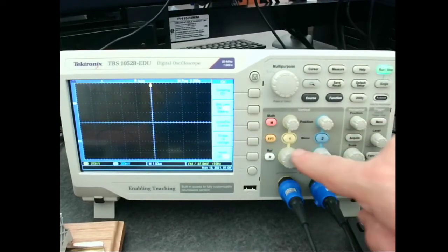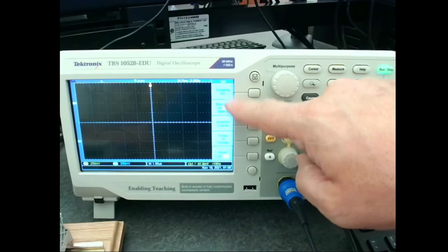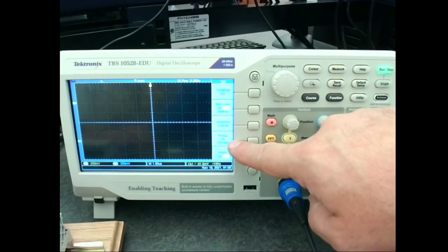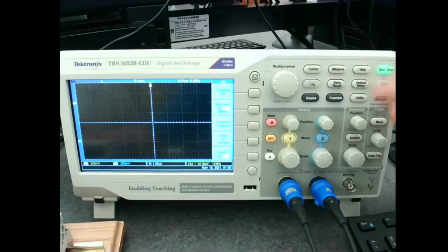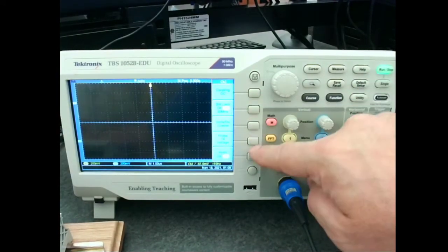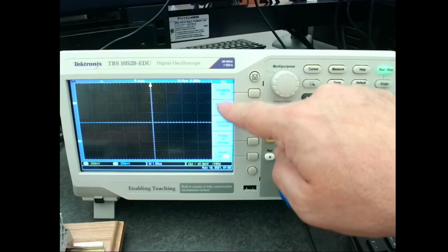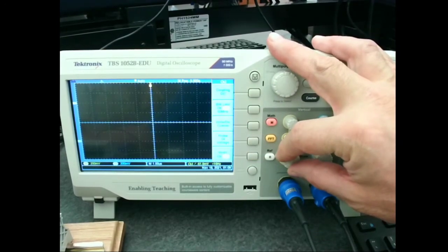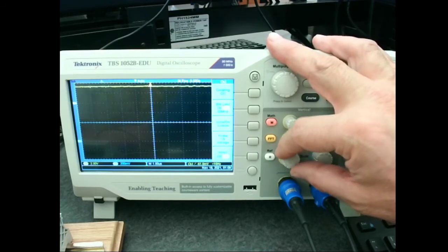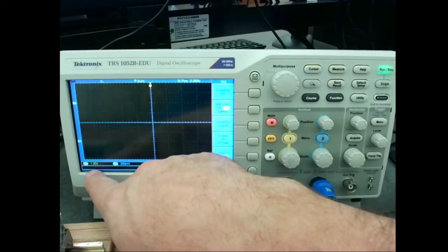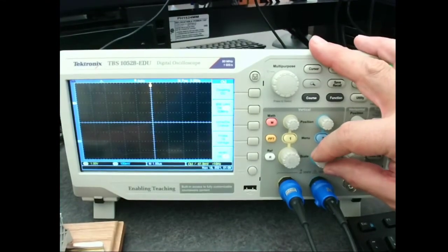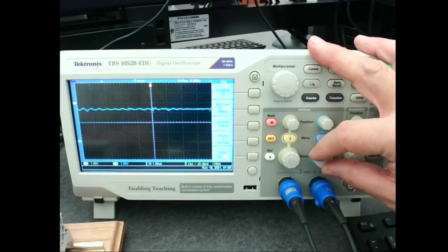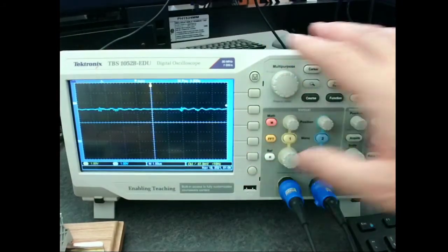All right. So again, let me walk through setting this up. I'm going to go to channel 1 and make sure it's still DC coupling and a 1x probe. Sometimes it'll even change that on you on auto set. I don't know why. So we just want to verify both our channels are DC coupling with a 1x probe, because that's the probe I'm using. And then I can adjust my voltages here. So I'm going to adjust the voltage to 1 volt per division, for both of those.